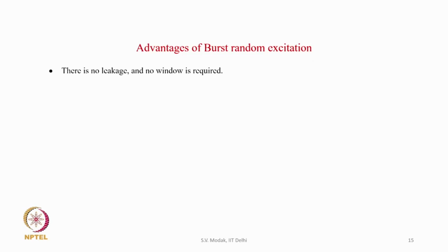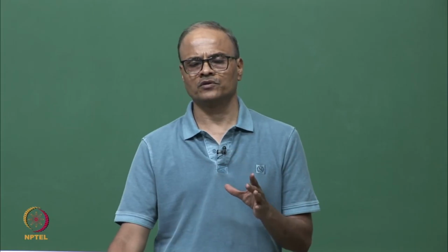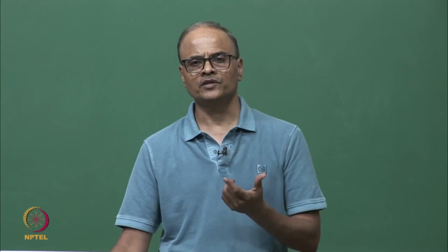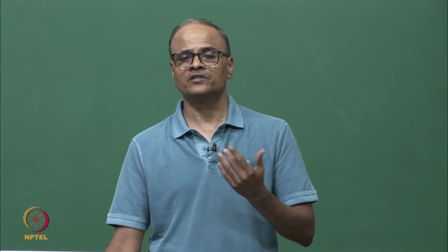The first advantage is that there is no leakage and no window is required. The use of a window is completely eliminated. Then, for each average, the burst part of the excitation signal is different. For each average, the burst part is generated independently, and hence this excitation allows obtaining a linearized estimate of the FRF in case the structure has non-linearities. Therefore, the range of force amplitudes used for excitation is broad, because first of all a random signal is used to generate the burst, and over the averages also the burst is different.